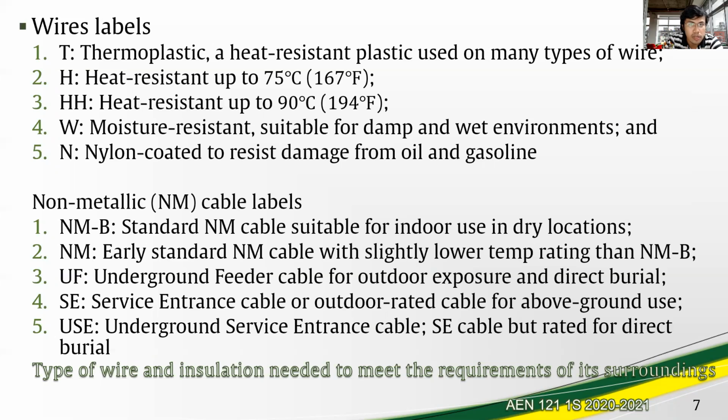We have the UF or underground feeder cable for outdoor exposure and direct burial, and SE or service entrance cable or outdoor-rated cable for above ground use. And lastly, we have underground service entrance cable and SE cable. This is just actually the SE, but rated for direct burial.